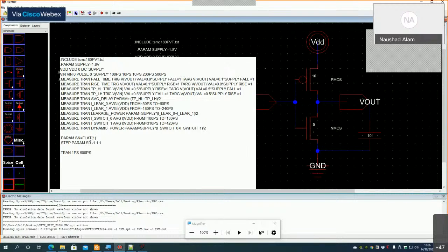distribution. Similarly for the P MOSFET, I will use the .param command. I can also use Gaussian variation, but let us take this one example. Flat, and I write 1 here. So this Sp will also be varied in the range of -1 to 1.